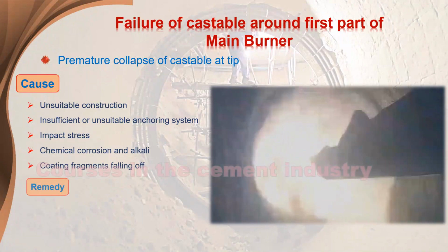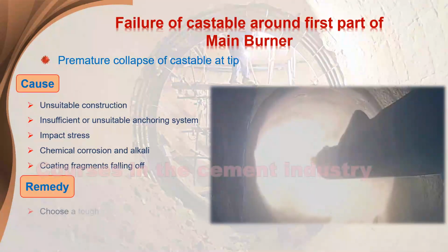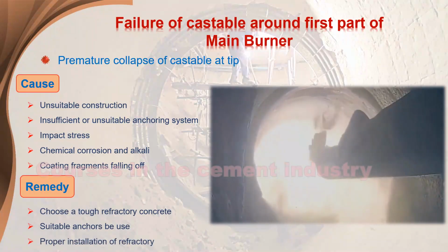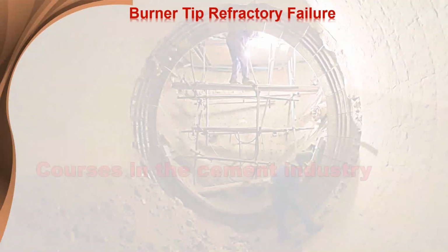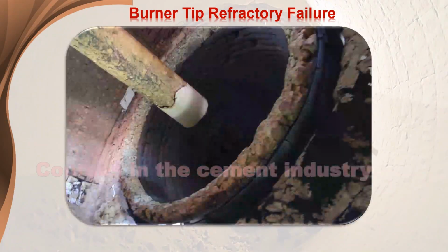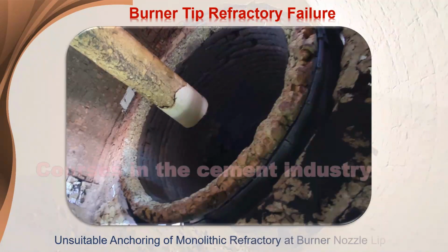Remedy: 1. Choose a tough refractory concrete. 2. Suitable anchors should be used. 3. Proper installation of refractory. Burner tip refractory failure. Unsuitable anchoring of monolithic refractory at burner nozzle tip.